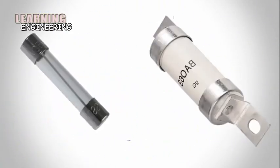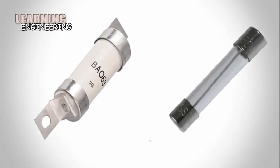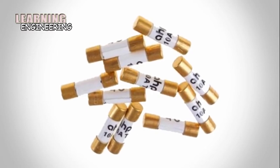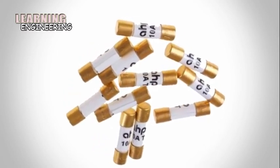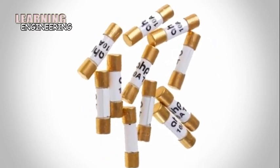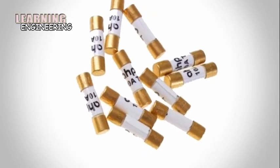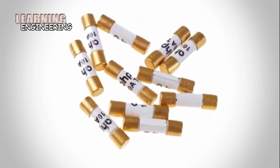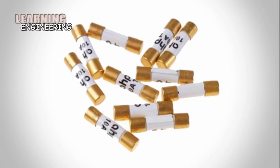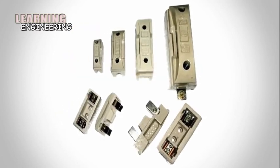The traditional fuse is a circuit element that is a one-time use element. That is, excessive current will cause it to open, and to restore the circuit the fuse must be replaced with a like element. They are often cylindrical and come in holders for somewhat easy replacement, but sometimes are soldered in place. They usually use a fusing element that is metal with a low temperature melting point that literally melts under overcurrent conditions. The cylinder is often made of glass to allow inspection of the fuse element to see if it is blown.